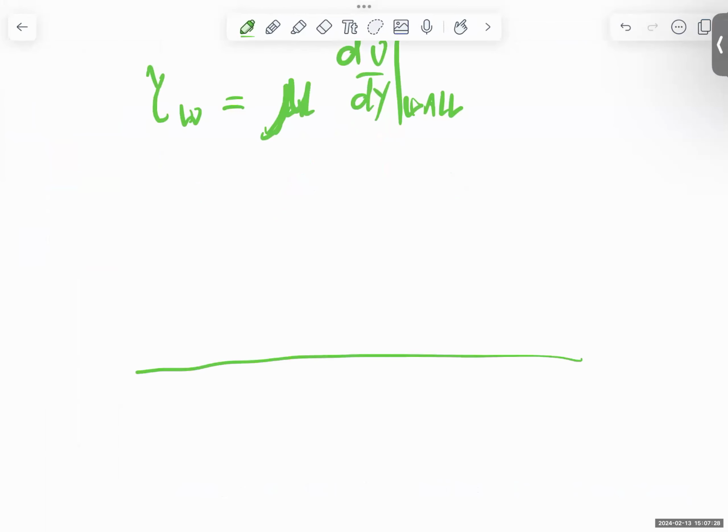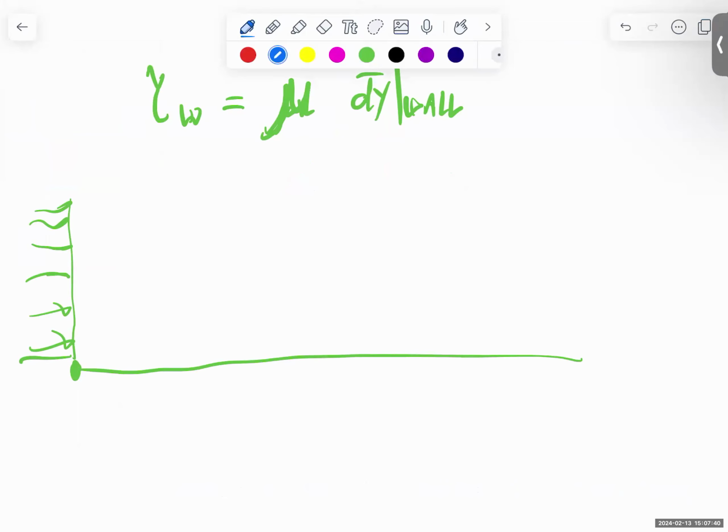And when you have a plate here, and you have this uniform boundary layer coming in like this, that moment it hits the plate, and that no slip condition affects just the near wall case, your velocity defect has a very sharp interface, just initially, very sharp, like this, because the rest of the flow hasn't heard about the plate slowing it down yet.